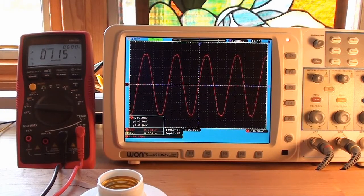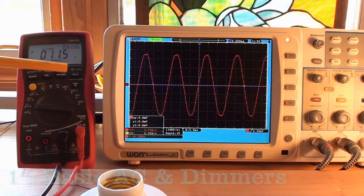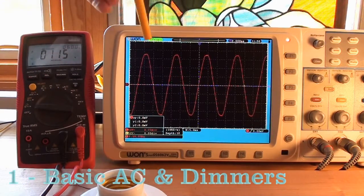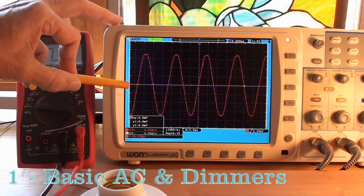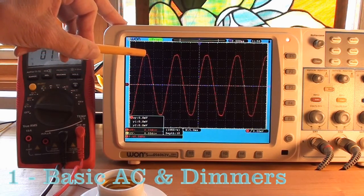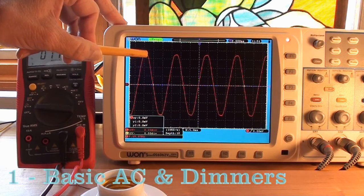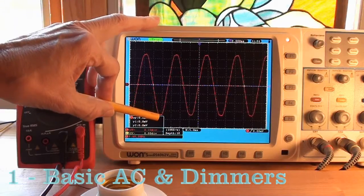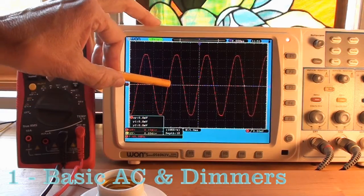So this is our oscilloscope display. It's showing voltage on the vertical axis and time on the horizontal axis. The purple line is 0, so as the voltage rises above 0, it gets up to about 170 volts or so peak. Each grid is 50 volts. And then it falls to the same amount below, and then it comes back to 0.